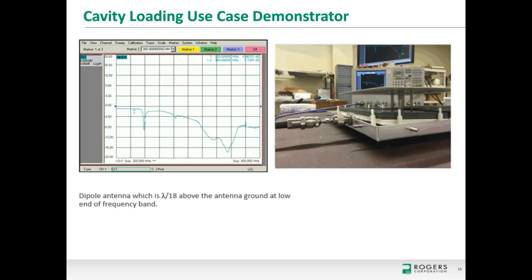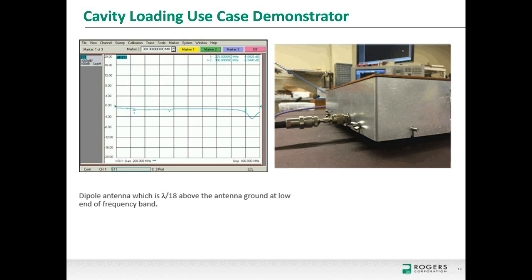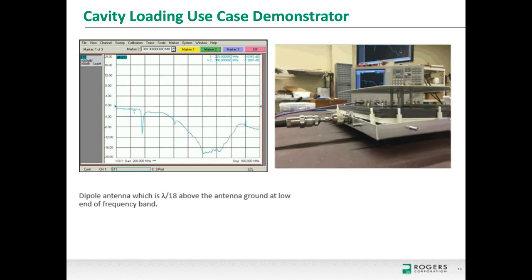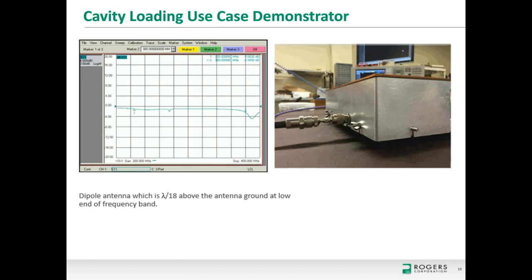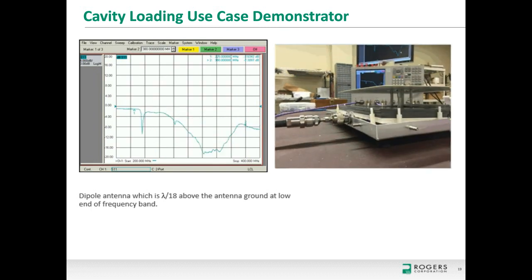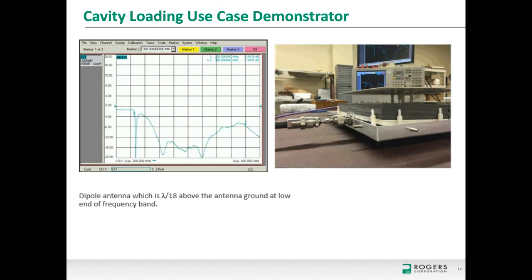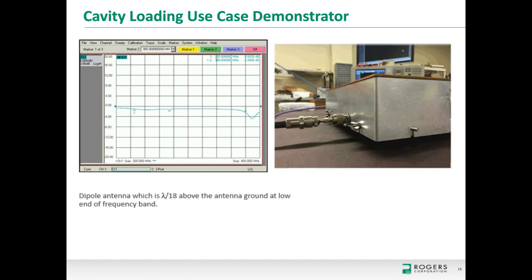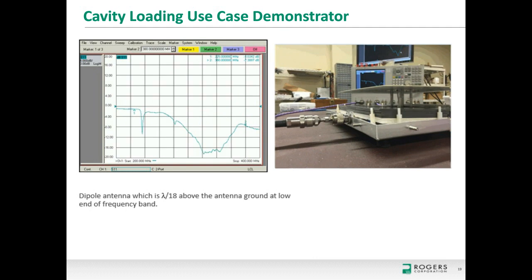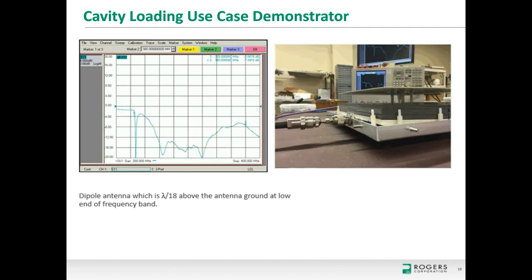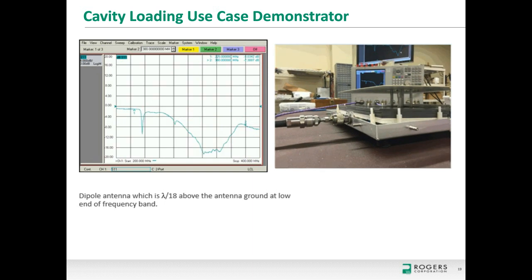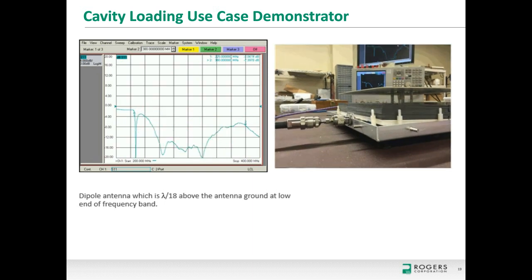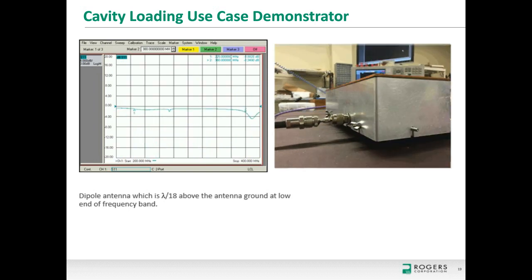Now, the second point is that if I were taking that dipole antenna and just loading a bunch of absorber material into it, I could see a similar effect. You can introduce bandwidth to an antenna by making it more radiative or by making it lossier. So at the end, we take basically a cap structure, place it over the outside of the antenna, and suppress the radiation. If my antenna were becoming wider in bandwidth due to additional loss, then when I suppress the antenna's ability to radiate, I wouldn't see much change in bandwidth. But because the bandwidth in this case is actually coming from antenna radiation, when I suppress the radiation, my bandwidth reduces. It's a basic way to show that the bandwidth enhancement I'm getting in this antenna is not a function of loss, but rather of the intrinsic properties of the material.